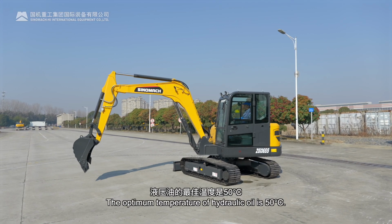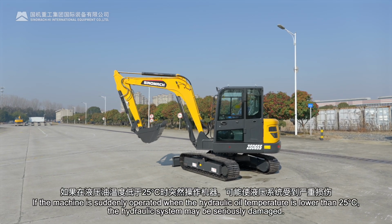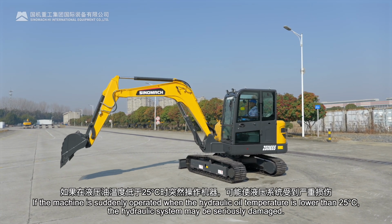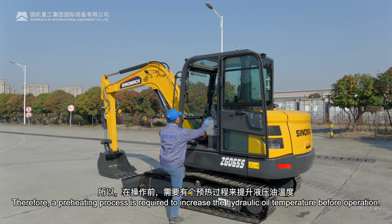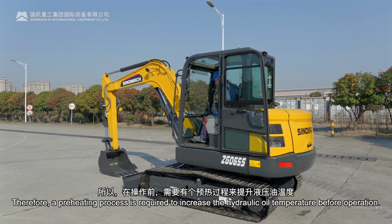The optimum temperature of hydraulic oil is 50 degrees Celsius. If the machine is suddenly operated when the hydraulic oil temperature is lower than 25 degrees Celsius, the hydraulic system may be seriously damaged. Therefore, a preheating process is required to increase the hydraulic oil temperature before operation.